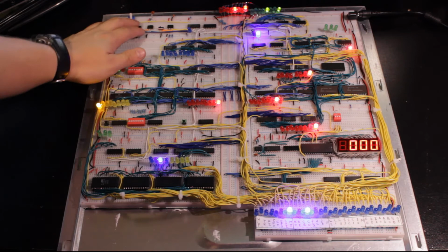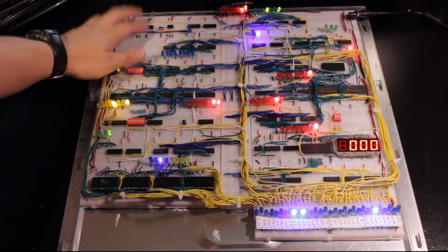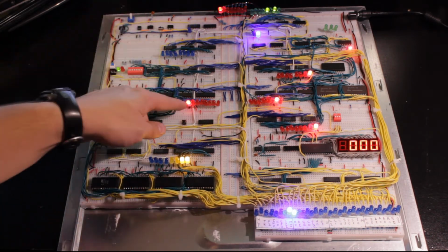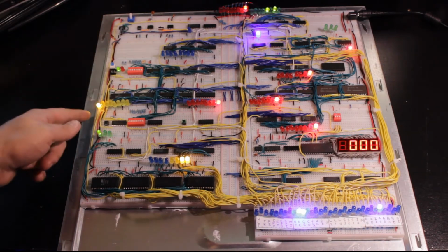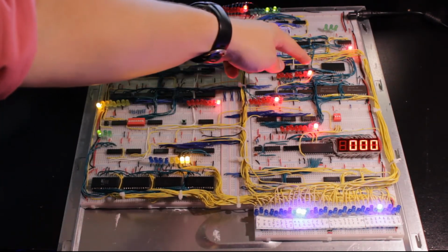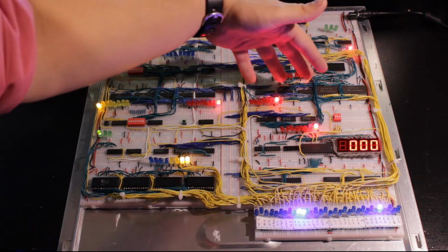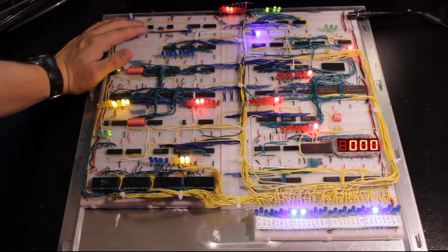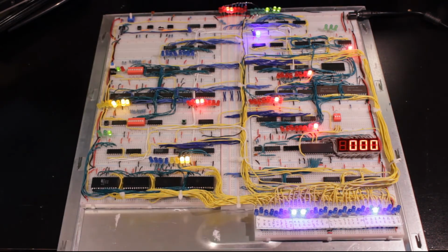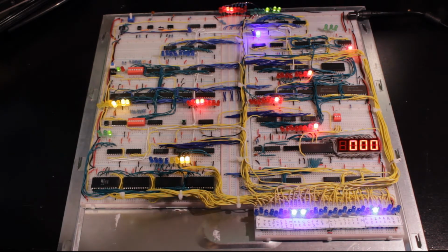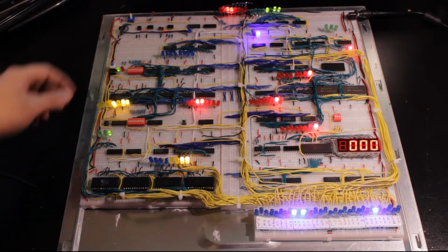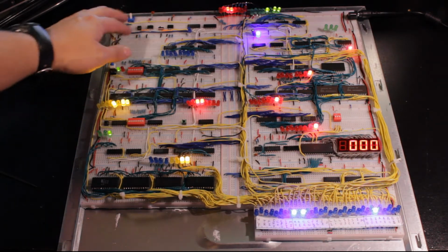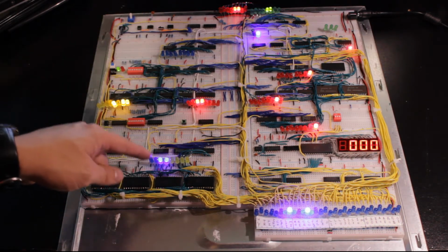We're fetching the next instruction, which is a store A command, and that's going to fetch the next byte, 0x80, for pointer memory. We go there, and we can see we took the value of the A register, and we stored it in that location, 0x80. Now we fetch the next instruction, which is subtraction. So we're doing computation to go backwards to get the other Fibonacci value. If we just did the addition to get the next one, we're doing subtraction to get the previous again. So we're doing subtraction, which is going to go into the instruction register.